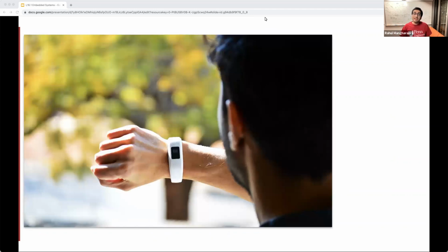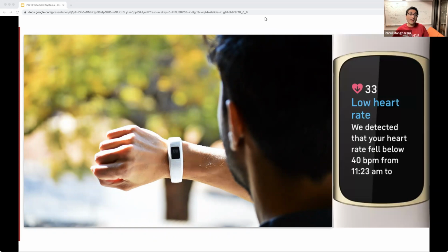Let's take a real world example so that you understand what these are. For example, a Fitbit might be looking at the angle of rotation of the wrist based on the IMU data that's coming in, and might be looking at the temperature or your pulse. The data is then sent over to your processing system, which runs the routines that were engineered by the Fitbit engineers in order to make some sort of decision and then to act on it. And that actuation might be in the form of generating an output to the screen, or might be recording the data into an actual subsystem.